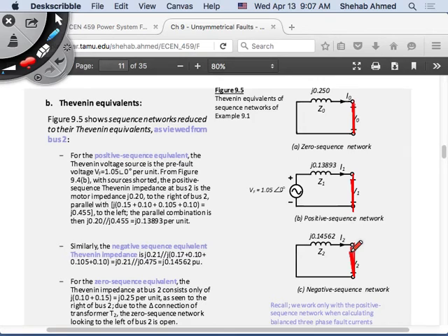So for a three-phase fault, or a three-phase fault to ground, it's a balanced fault. For a balanced fault, how do you calculate the fault current? We know that it's only the positive sequence circuit, right? But fine, you can put a short circuit on all of the sequence circuits. There will be no current flowing here, no current flowing here, since there's no voltage sources. We are left with only current flowing in this circuit, right? So it's this voltage source divided by this impedance.